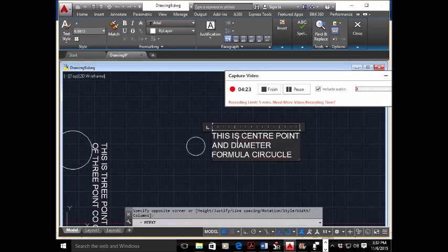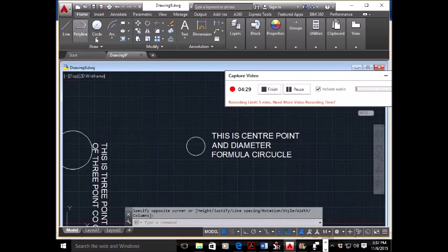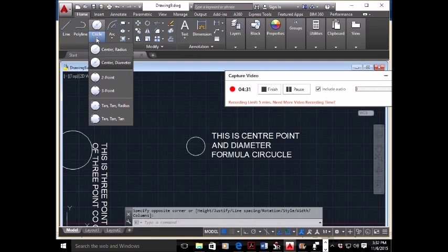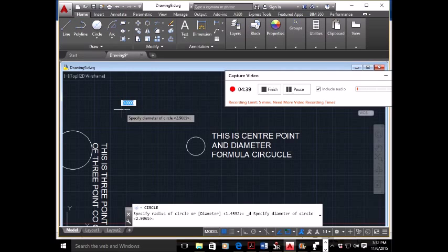To format text in a TrueType font with boldface or italics, or to create underlined, overlined, or strike-through text for any font, click the corresponding button on the ribbon. SHX fonts do not support boldface or italics. To apply color to selected text, choose a color from the color list. Click Other to display the Select Color dialog box.